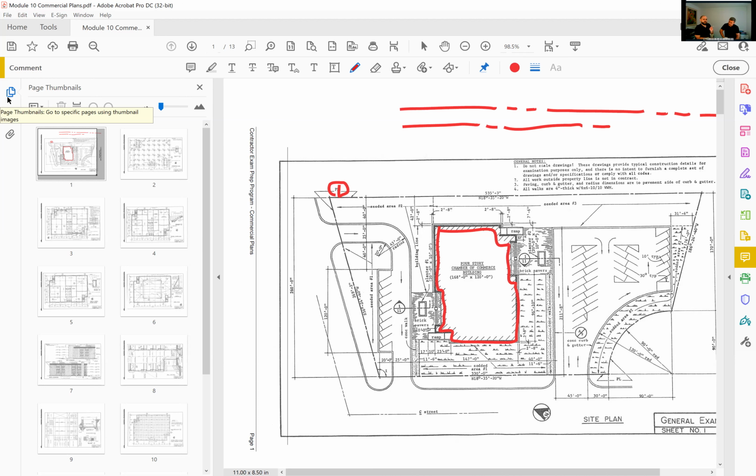when it's asking you for those sorts of things, you need to look for the wall section. Like what kind of block you're using, or what type of drywall, or insulation. Insulation's a big one. Floor material, you usually find it there. Does it have a baseboard? What's the ceiling made out of? What's the height of the window sills? That's another big one. I don't know if they'll ask that too often on the exam, but in the real world, that's where you'll find it.